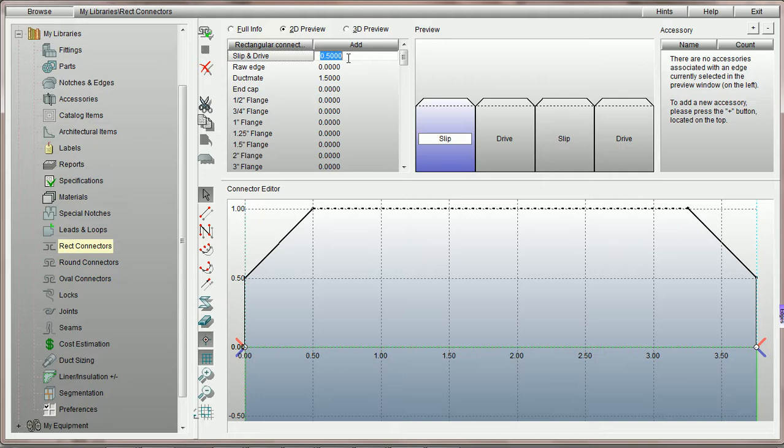The add parameter is actually in PractiCAM the notch back. What that would mean is that if we've got a 1-inch connection and we say to add or notch back the connection by a 1/2 inch, it would mean that we're leaving a 1/2 inch of length of material at the end of the fitting for the connector. Therefore, we would lose a 1/2 inch of material.